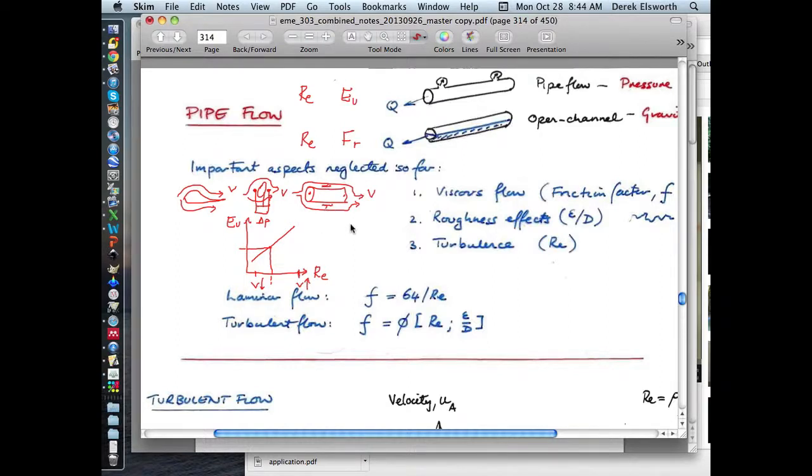If you take the internal flow, which is what we're going to be interested in now, then the velocity is quite obviously going to be through the pipe. You can imagine that you'd have these same viscous flows acting on the wall of this pipe. And you could also imagine that there would be a pressure drop between the upstream and the downstream. And so, philosophically, it's really not very different from this. You get a pressure drop that you're interested in here, and you want to know what the force is that's acting to be able to calculate if your pole gets snapped off.